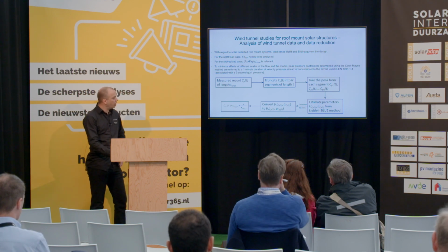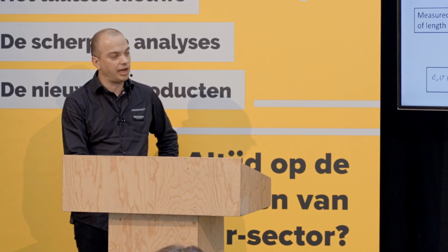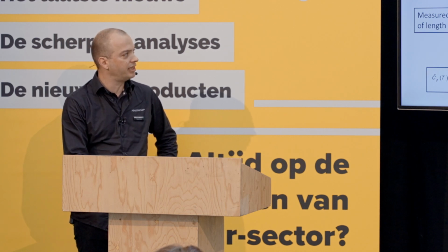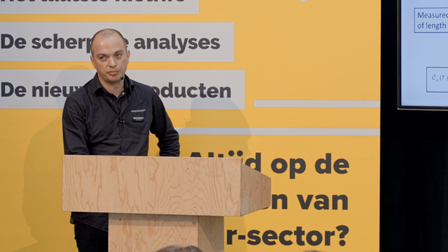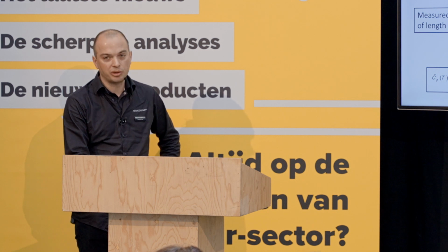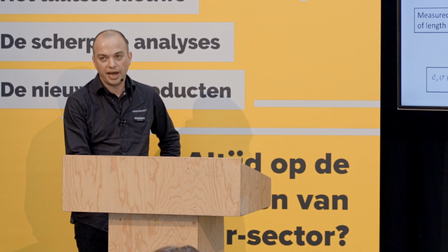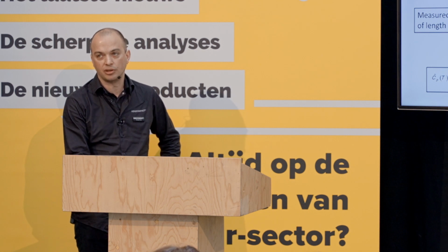There are 2 load cases which govern the design and which must be analyzed: uplift and sliding. For the uplift load case, the maximum vertical force needs to be analyzed from the wind tunnel data. For the sliding load case, it's the vertical force plus a horizontal force divided by the static coefficient of friction.